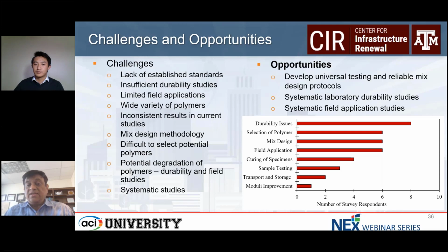So we feel there are many opportunities in this area, and the benefits are sometimes very important here. Polymeric treatments can be faster, and can improve certain types of soils. Also, mixing is very quick in the field. Like Jason clearly mentioned, with the different solution or emulsion forms, you can really spread it. You can do it also on slope configurations, depending on what type of infrastructure you're dealing with. You can do it very nicely with spraying and also mixing, and that also provides an opportunity.